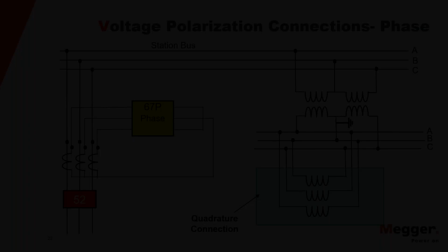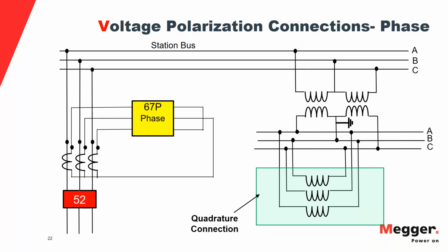So the question is, could you please explain how zero sequence voltage and current can be provided by the fourth auxiliary PT if the primary PTs are connected in delta configuration? Yes, we can have a secondary connected in open delta because the PTs have multiple cores on the secondary. We can use one secondary core for the phase elements, and another secondary core we can connect in open delta, then we can get the fourth PT for the directional element input.